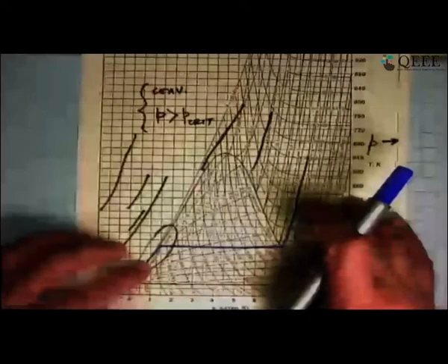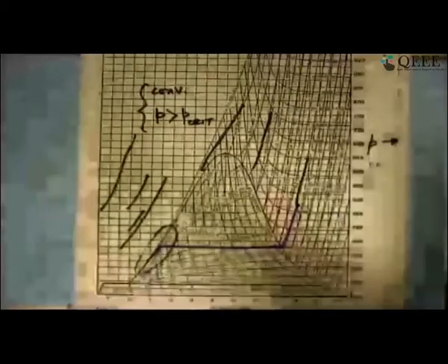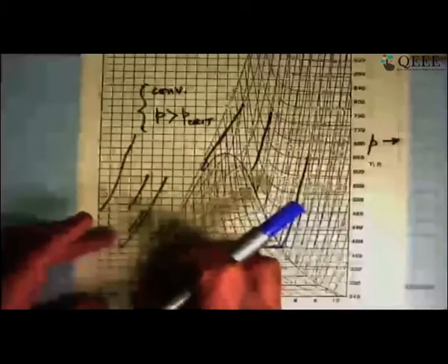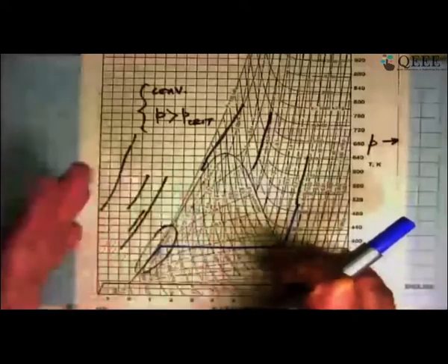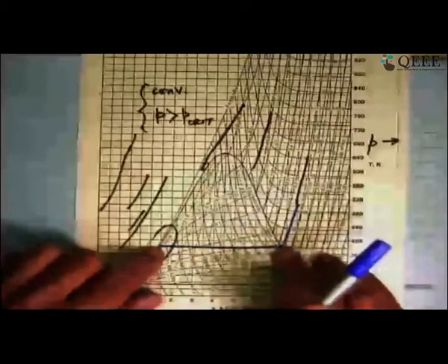So what was one thermodynamics problem becomes three things in sequence in the heat transfer part, one after the other, where we provide this particular design for heating the liquid to saturated liquid state. Then we provide a region where we convert the saturated liquid into saturated vapor. So dryness fraction 0 here, dryness fraction 1.